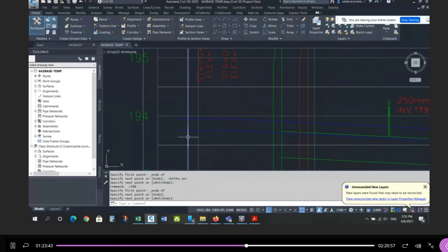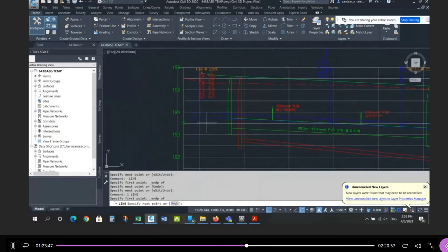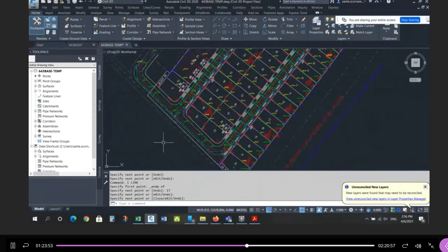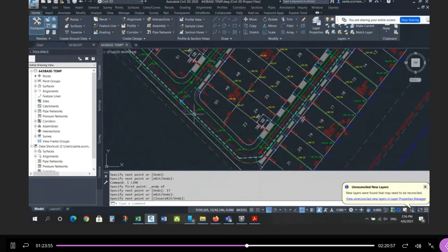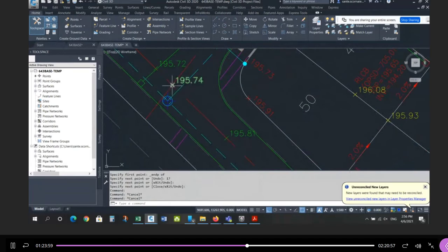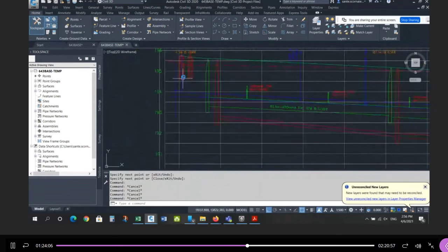Okay. The elevation of this actually comes from 1.7 below this road. There's really where the top of the water main is, right? Because this is a T intersection. So this water main would be below this center line. So whatever the center line is here, down 1.7, that's the elevation of the top of pipe on this side of the road, technically.